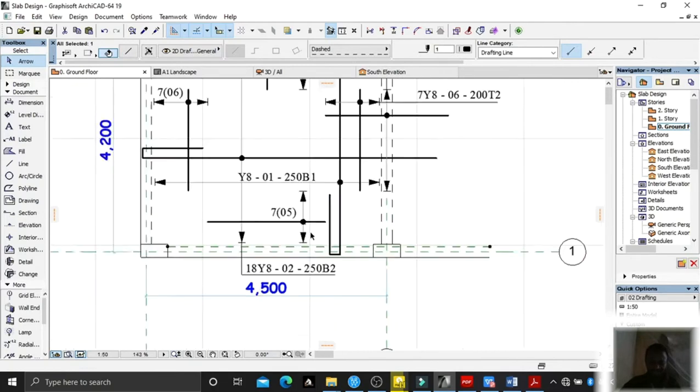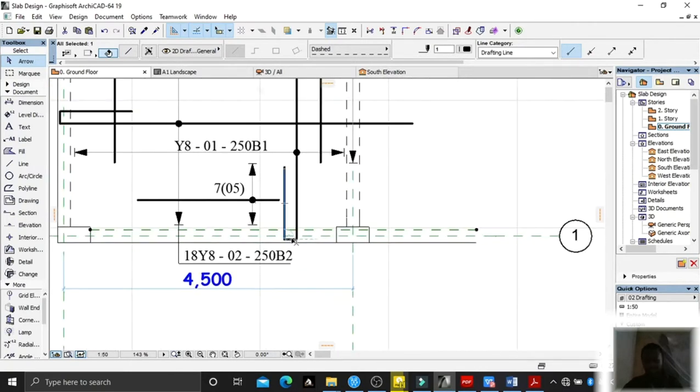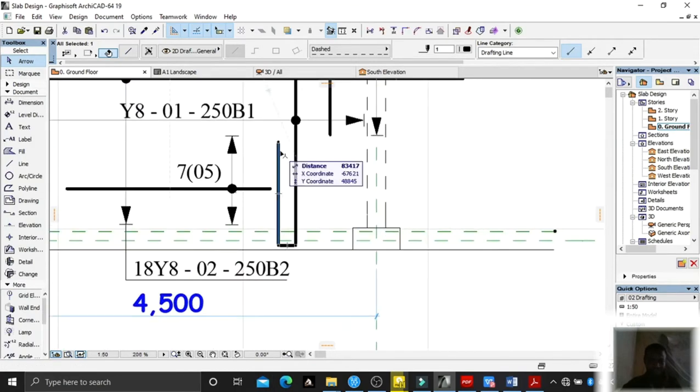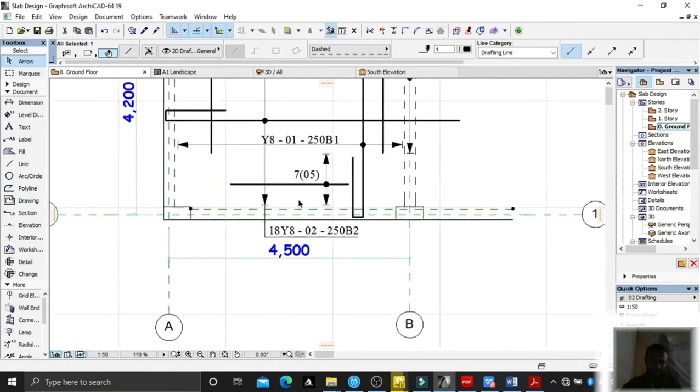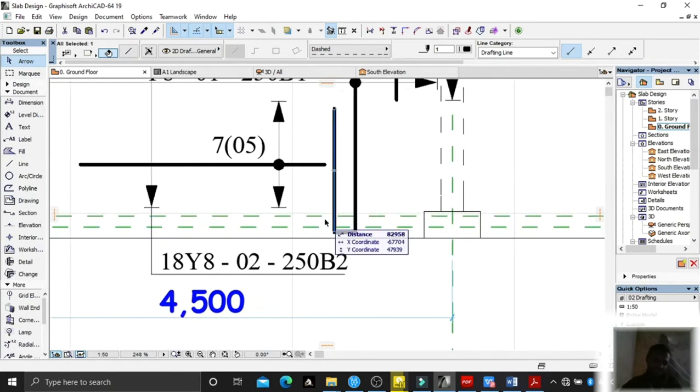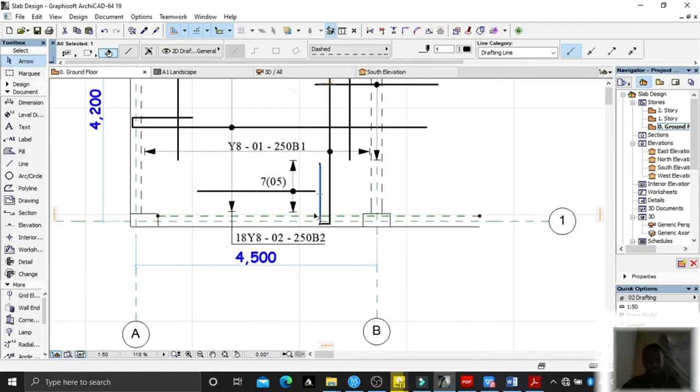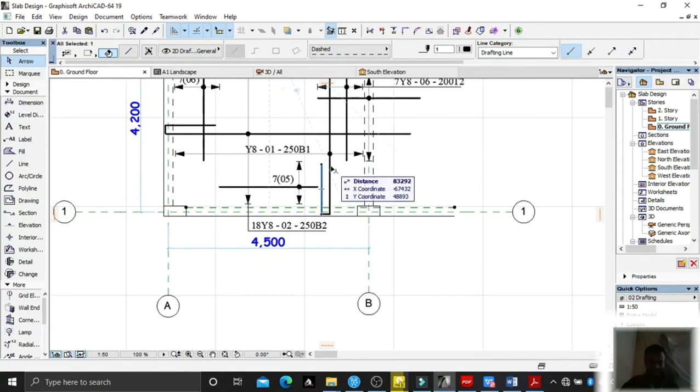Again, you find this bar has some kind of weird thing going on here, where I'm pointing with my cursor. This is what we call planking, and it's basically done as 25% of the shutter span. That is 25% of 4.2 meters. So from this edge to this point, we have the 25% length of the planking. That's how we come up with bottom one.